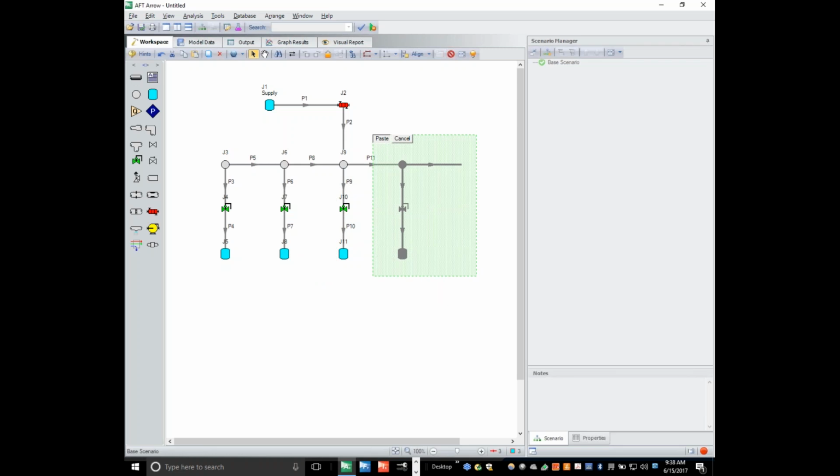3, 4, and 5. And this is the only pipe we don't need, so we'll select it and we can delete it. Then we simply need to make sure that pipe 2 is connected, and we are going to reverse the directions of these pipes just so that we don't have to look at any negative flow rates. Even though it won't change anything, we just want to make sure everything looks nice. All right, I'll get these out of the way.